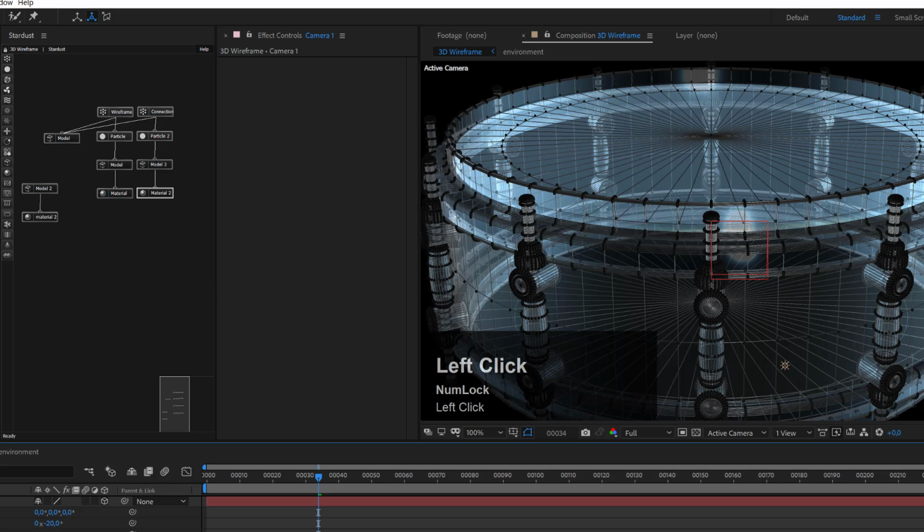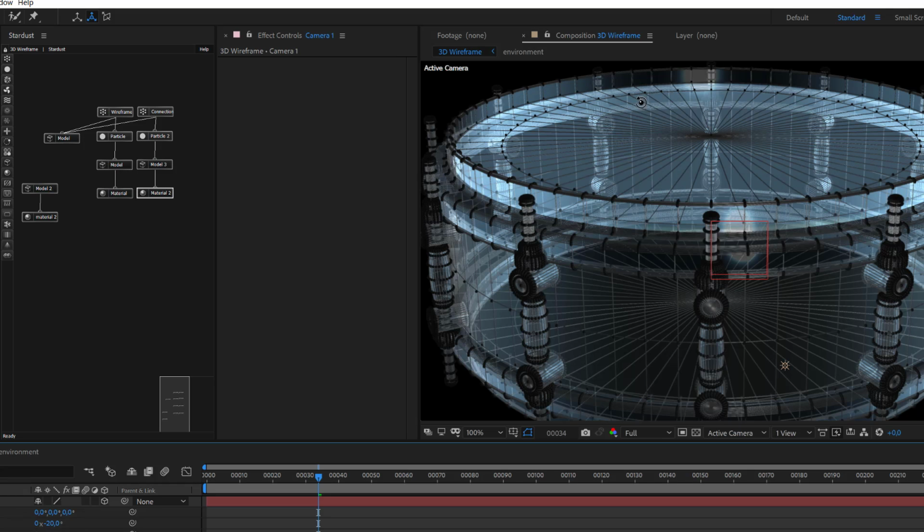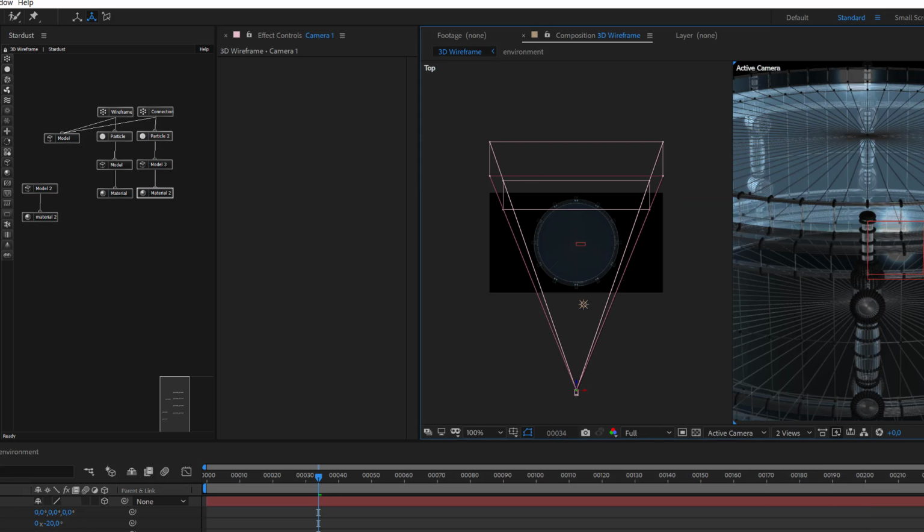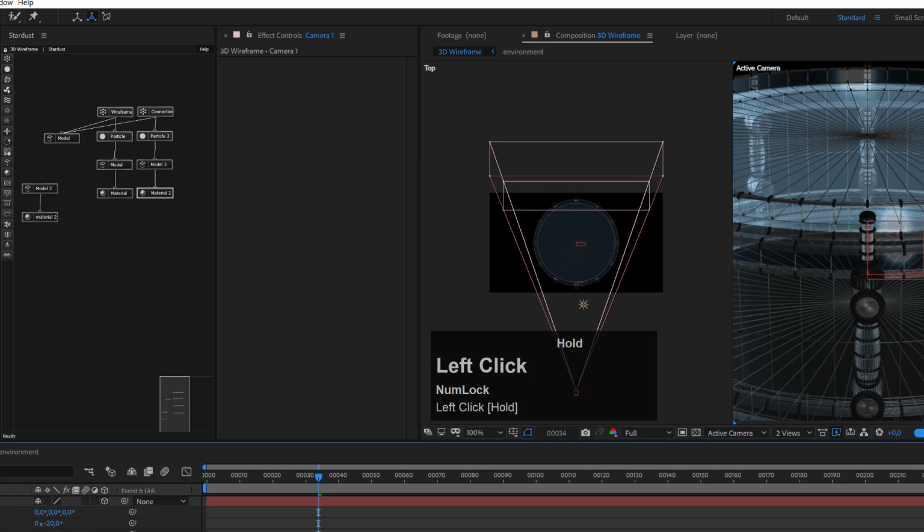So if I go to my camera now and press AA and enable this, you will see that something is happening, but you will also see that somehow it looks a little bit strange. So let me quickly shift my focal point to the right point, and you see that it is way back there, and I want it to be here right in the front of my model. So let's just shift this right to the front of my drum here. Oops, now I changed the aperture. I didn't want to do that. I just wanted to shift the focal point. Something like that looks good. Okay.